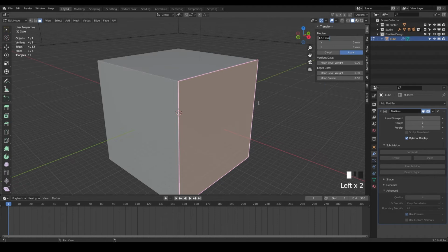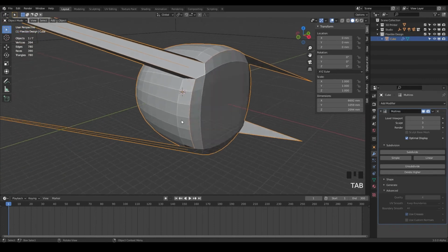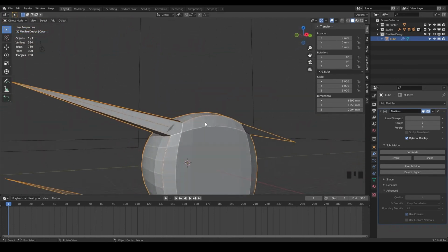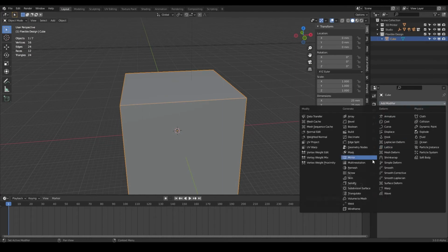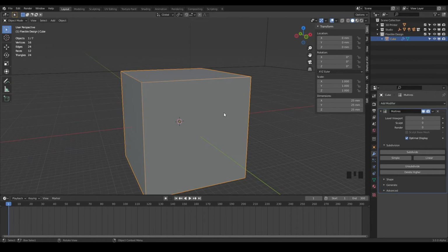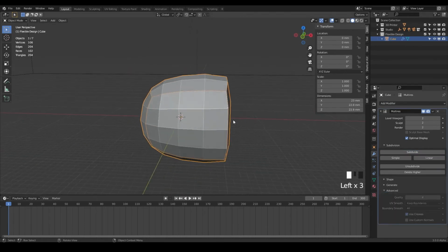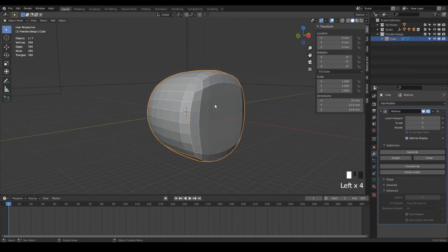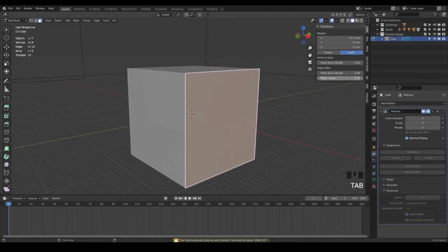And then if we go back to object mode, it has gone crazy. So not sure. I'm in alpha mode, so maybe that's a bug there, but let's just erase that. It's non-destructive, so it's totally fine. Add the multi-res, and let's make sure we've got use creases, and let's subdivide a few times. There we go. So now Blender is taking the edge crease into account.